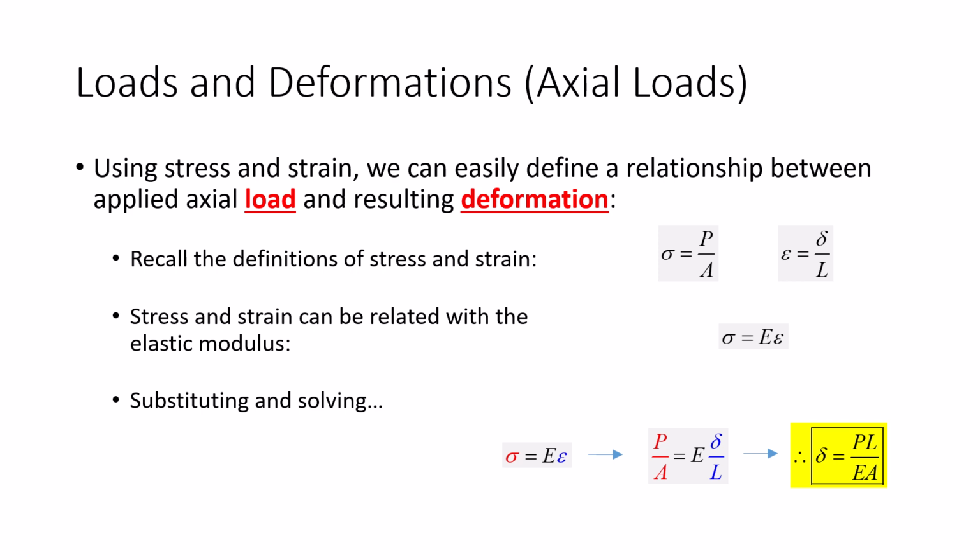These three gray boxes right here are essentially the three concepts that we've been defining for these first few lectures. We've been using concepts in equilibrium and cross-sectional properties to turn forces into stresses. Then we use compatibility relationships to turn deformations into strains. And then we can relate stresses and strains with material properties, with constitutive properties, such as the Young's modulus.